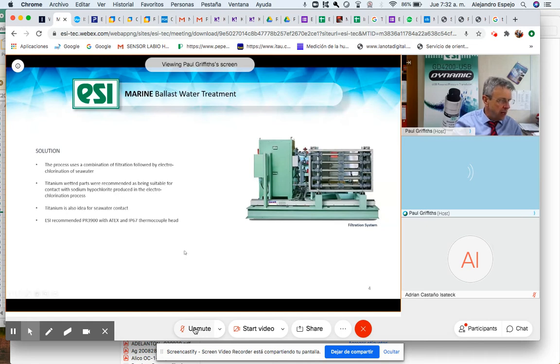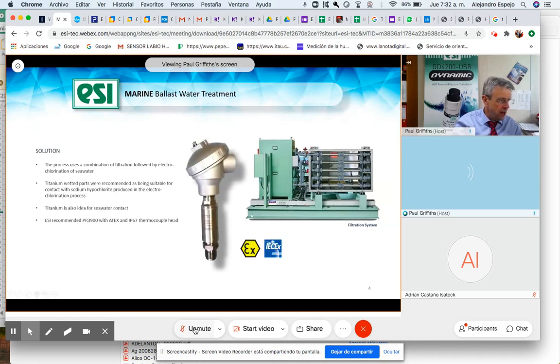So the first application we had, the customer wanted to have this type. You'll be familiar with this, a thermocouple head. So it's a field accessible connection point where you can bring the cable through and easily connect the cable to the transmitter without any difficulty, with easy access, and then you can close the lid and it's weatherproof. So this is suitable for shipboard, outdoor use.